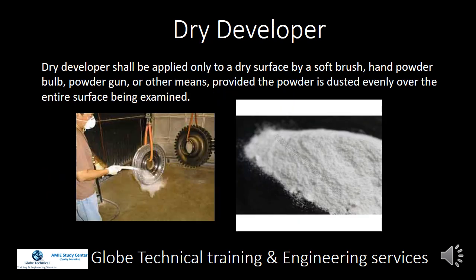Dry developer. Dry developer shall be applied only to a dry surface, by a soft brush, hand powder bulb, powder gun, or other means, provided the powder is dusted evenly over the entire surface being examined.